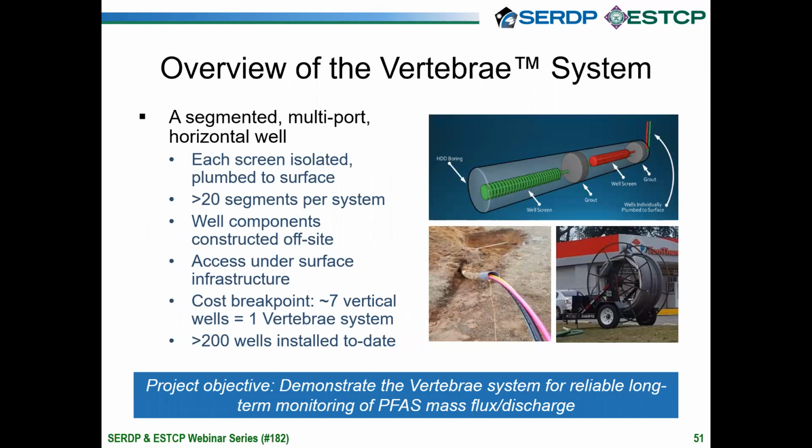So simply stated, the vertebrae system is a segmented multi-port horizontal well that was developed by a company called NREX. As you can see in the picture in the upper right, each screen, which is depicted in green and red, is separately plumbed to the surface and separated by a grout seal. The picture on the bottom left shows several color coded risers, and each of these is connected to a different screen. An individual vertebrae can be installed with more than 20 screen segments for the whole system.